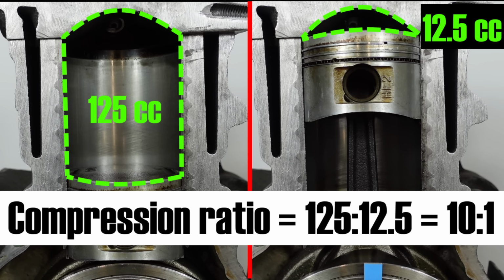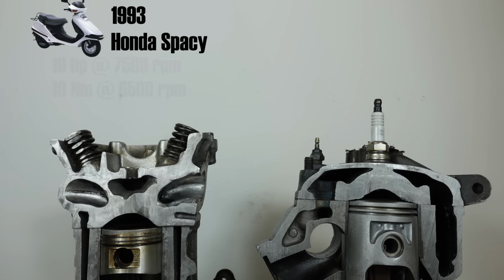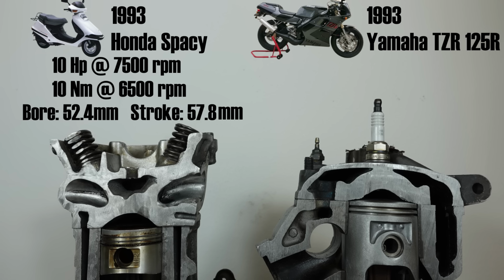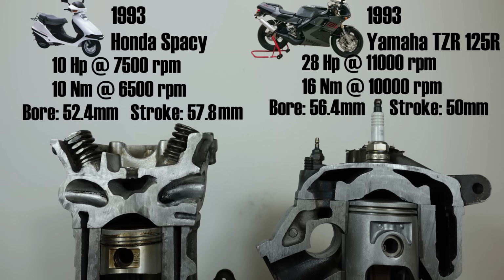Now, both of our demonstration engines are actually single-cylinder 125cc motorcycle engines. Our 4-stroke is from a 90s Honda Spacey scooter. It makes 10 horsepower and 10 Nm of torque and has a bore of 52.4 mm and a stroke of 57.8 mm. Our 2-stroke engine is from a Yamaha TZR Belgarda sports bike, which is also from the 90s. It makes an impressive 28 horsepower and a less impressive 16 Nm of torque and has a bore of 56.4 and a stroke of 50 mm.